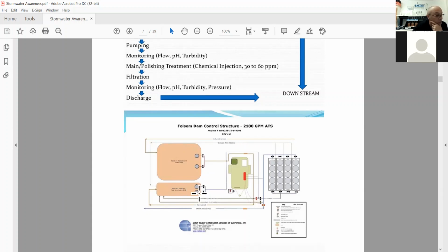An active treatment system is a portable, temporary, small wastewater treatment system that generally treats from 200 gallons per minute to over 1 million gallons per day, which is about 700 gallons a minute, 24 hours a day. An active treatment system protects natural waterways from the negative consequences of construction, land disturbances, or other man-made water quality problems. The active treatment system is the BMP of last resort.